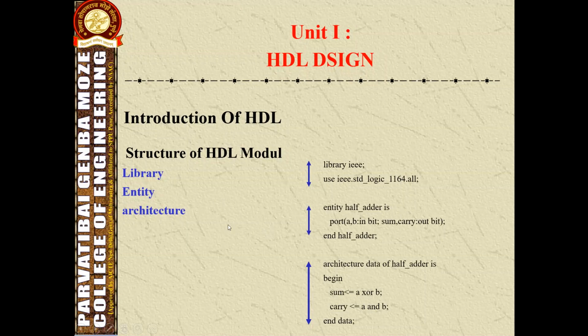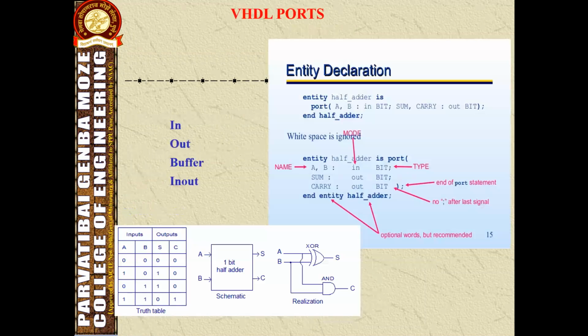Today in this lecture we will begin with how the entity will be declared and what are the ports used for declaring the entity. This is the entity declaration. In this slide, the figure of a half adder is shown, and this information will be mentioned in the entity.